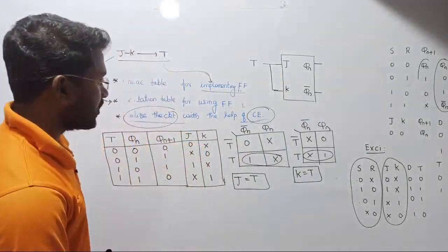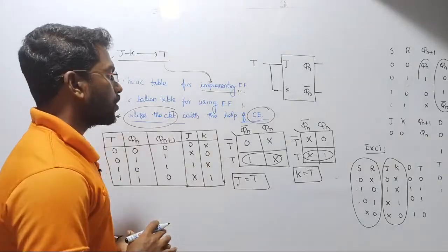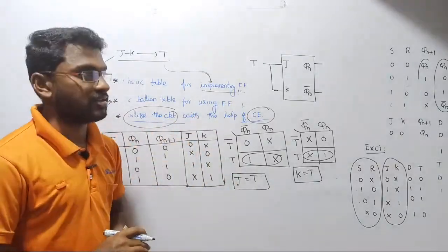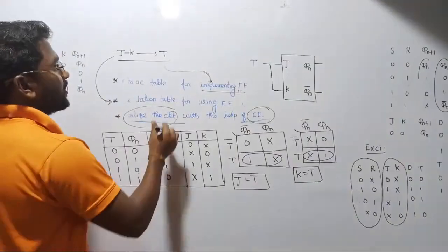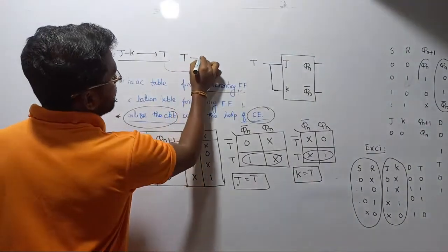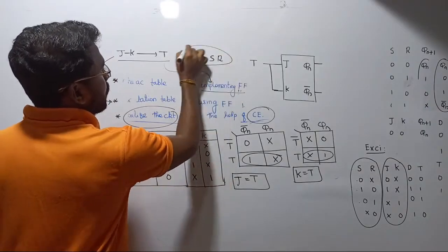Okay, fine. I hope things are very clear to you all. Now, in order to get a very clear idea regarding these circuits, let us take some other possible combinations. We have designed many things here, right? So now what shall we do? Let us take T flip-flop. Let us design SR flip-flop with the help of T flip-flop.